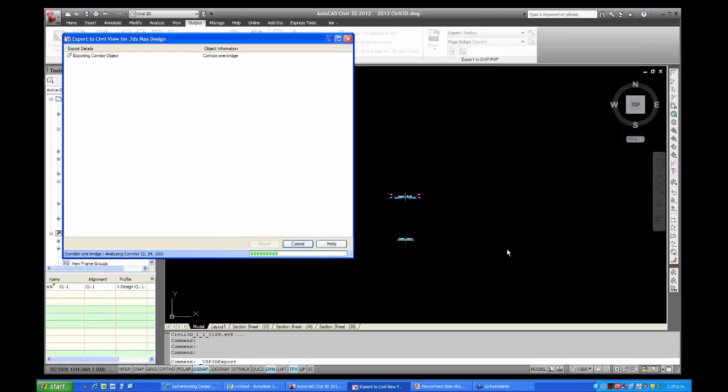For 3ds, you only need, as I say, the surfaces for visualization, the top surface of your corridors, and that's what this is going through and exporting at the moment, and any line work which happen to be feature lines. They need to be feature lines rather than polylines to export them. So wherever you can, reduce the amount of data that gets transferred through. It's what's effectively a graphics program that it's going through to. It doesn't need all that extra detail.